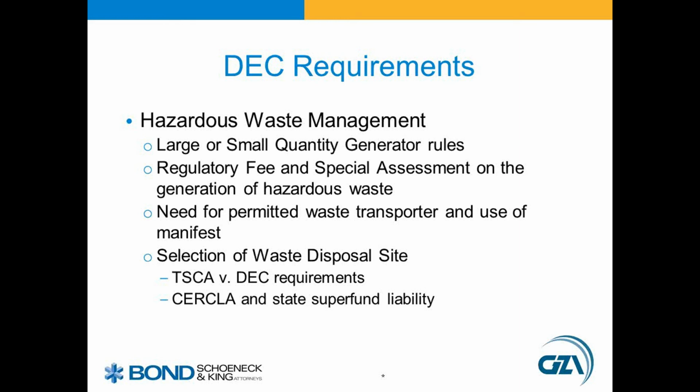Even if you're dealing with a PCB impacted material less than 50 parts per million, it would still be contaminated. It would still contain PCBs. Still has potential issues associated with CERCLA and state Superfund liability if that material is taken off for disposal at a landfill. So the concern is, again, renovation. You're buying a piece of property. You know this property has been constructed or renovated during the time period that's been indicated, the 50s into 1979. So it's a potential issue, a potential concern that there could be a cost associated with operating and, in fact, then renovating that facility.